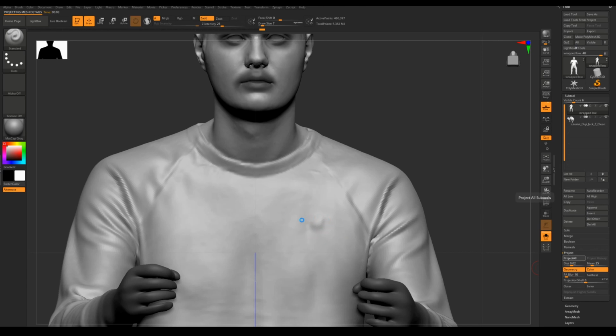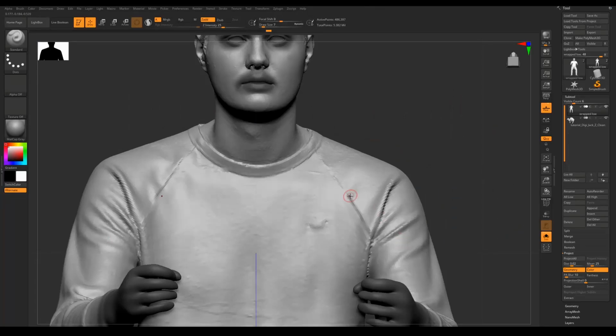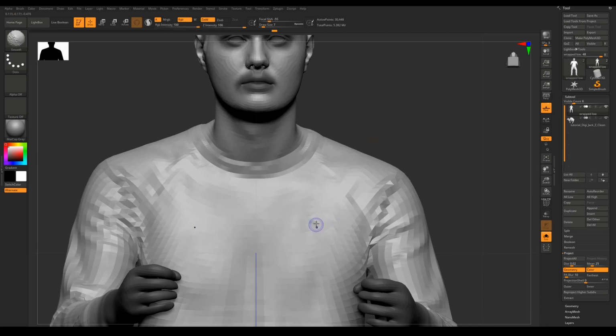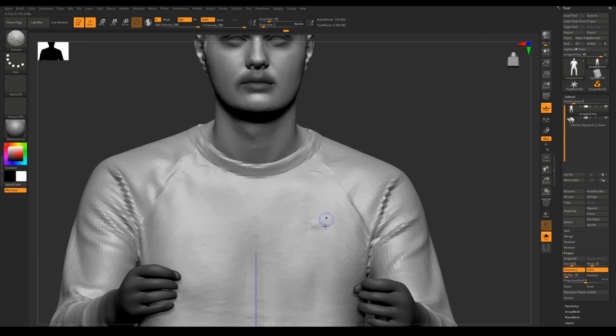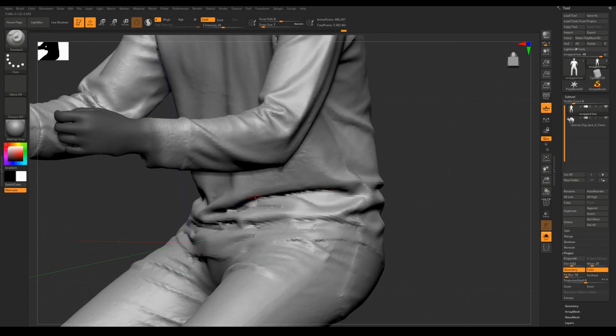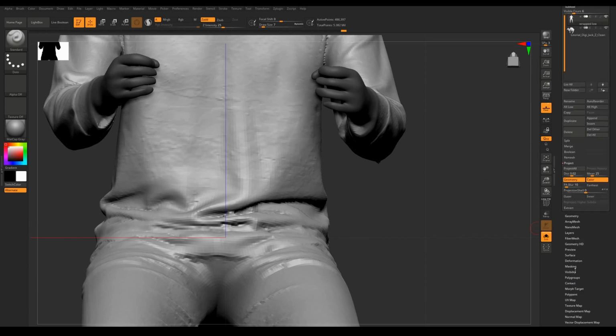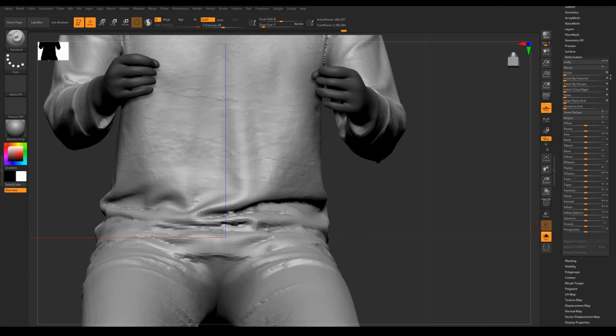So in the final model, there's a logo on my shirt, as you can see here. I'm going to get rid of that logo because it actually shows up on the geometry as well. So I'm just going to go in and smooth it off a little bit on each subdivision. There we go. Not bad. We got a few errors around here. So just to smooth off any spiky parts, I'm going to go deformation, and then put this on like 3, or probably 1 actually, or even the crisp edges. That's better.